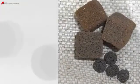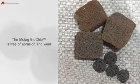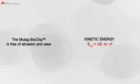These pictures present breakage and abrasion. The abrasion is caused by the high kinetic energy which affects the carriers in the moving bed once they are colliding with the tank walls or once they chip off and abrade each other at high filling rates when colliding. On the contrary, there is no wear or abrasion on the Mutag biochip. Therefore, no maintenance, exchange or replacement is required due to the very low mass compared to its size.